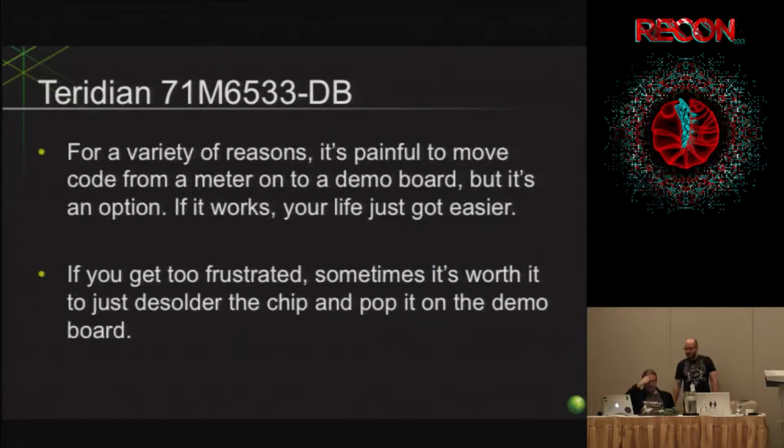A lot of times when you are dealing with a live meter and you're trying to figure out what's going on, like in a lot of hardware gigs, the first thing you want to do is dump firmware. Often we find that the SoCs are fairly locked down, and it's a pain to do that directly on the device. So one of the first tricks we pull, if we immediately fail at pulling it off and have to up our game a little bit, is to take a hot air gun, or Chip Quik in this case.